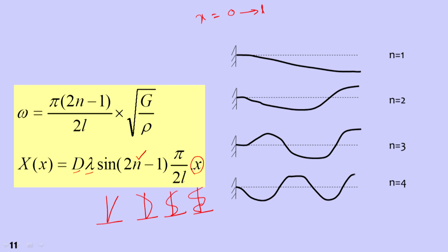So this mode shape will give us a deflection profile of the structure, and then we need to solve the time function. So that is, X of x we are getting, and we need T of t. So this is the overall displacement. What we had discussed in multi-degree of freedom systems is x comma t is equal to phi q. So this T is representing the q term and X is representing the phi term. So now how do we use this phi term, that is the deflection profile, and find the response of continuous systems? That we will discuss in the next class.